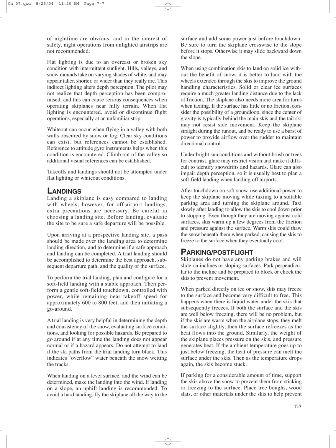Reference to attitude gyro instruments helps when this condition is encountered. Climb out of the valley so additional visual references can be established. Takeoffs and landings should not be attempted under flat lighting or whiteout conditions. Landing a skiplane is easy compared to landing with wheels, however, for off-airport landings, extra precautions are necessary. Be careful in choosing a landing site.